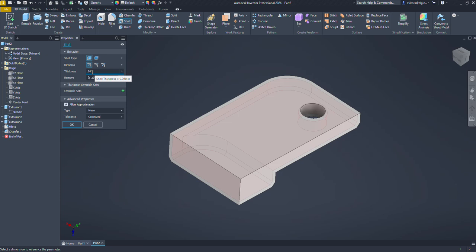And one thing you'll notice, those of you who are taking my class, we talk about machinist talk or machinist speak. Especially in the United States here, we talk about like 0.06. That's 60 thousandths of an inch. And I know you were taught a little differently when it comes to some of this in math, the way they reference it. But that's how it is in manufacturing. If it's 0.006, that's 6 thousandths.